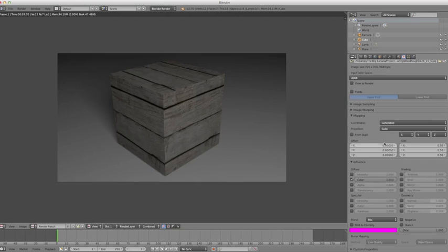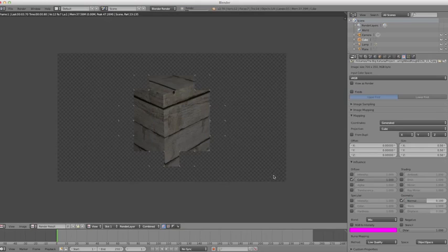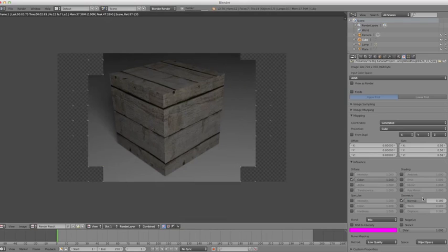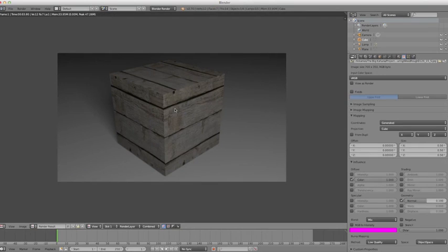So anyways, we got this going here with the color slider turned on. Again, we can use this to affect specularity, bump, the kind of ambient shading we've got going on, and all the things like that. So if we turn the normal on, usually you'd want a black and white image to affect certain things, but if you turn that on, put it down to something low, you can see we've already got a little bit of this bumping going on here.